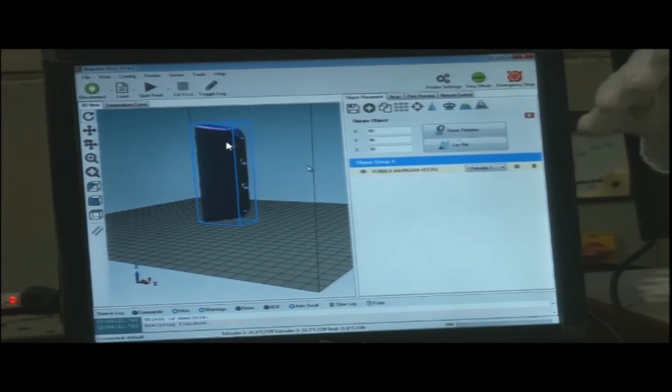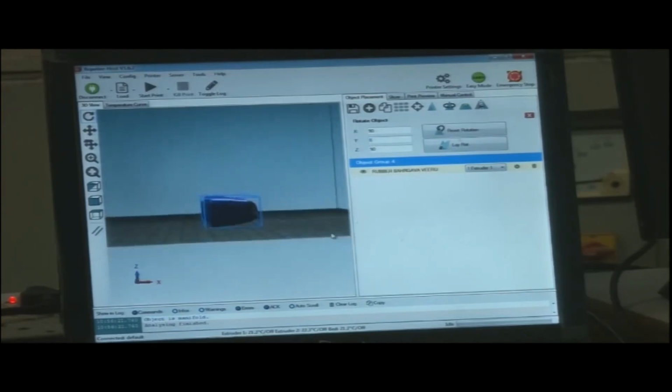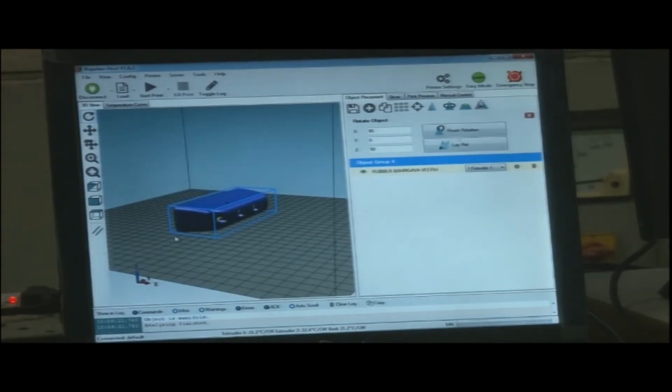Total time means total cost of the product will also increase, because in the product cost function the machining time is one of its factors. So this is not a very good position to manufacture. So we can opt to select the flat position and orient the job in proper place and position.